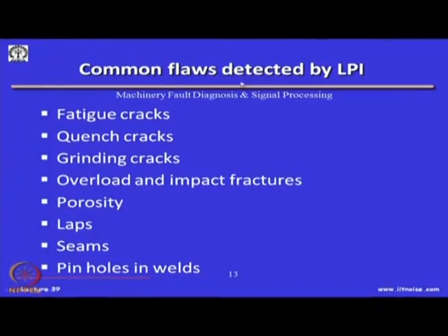Some of the common flaws detected by LPI, or liquid penetrant inspection, are fatigue cracks, quenching cracks during heat treatment, grinding cracks, overload and impact failures, porosity, laps, seams, and pinholes in welds. These are things too small to detect carefully with ultrasonics or eddy current, because the resolutions here are so fine that they may be in the noise floor of an ultrasonic or an eddy current system.